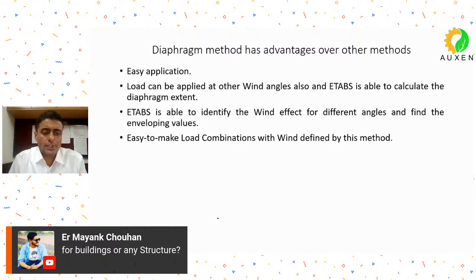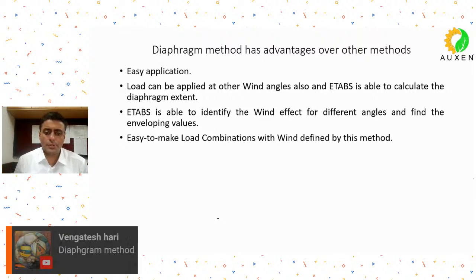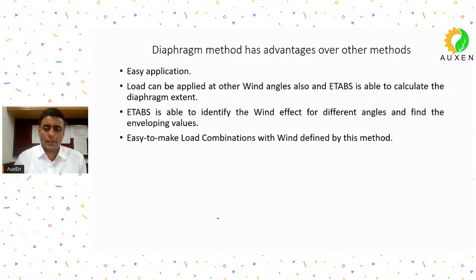Mike is asking this question: which method is better, is it for buildings or structures? No, I am talking about buildings right now, general buildings. Of course, in a complicated structure, you cannot expect the software to do auto load application. You will have to manually calculate and apply. That's quite sure. But here we are asking about building type structures. So the diaphragm method, what are the advantages it has?